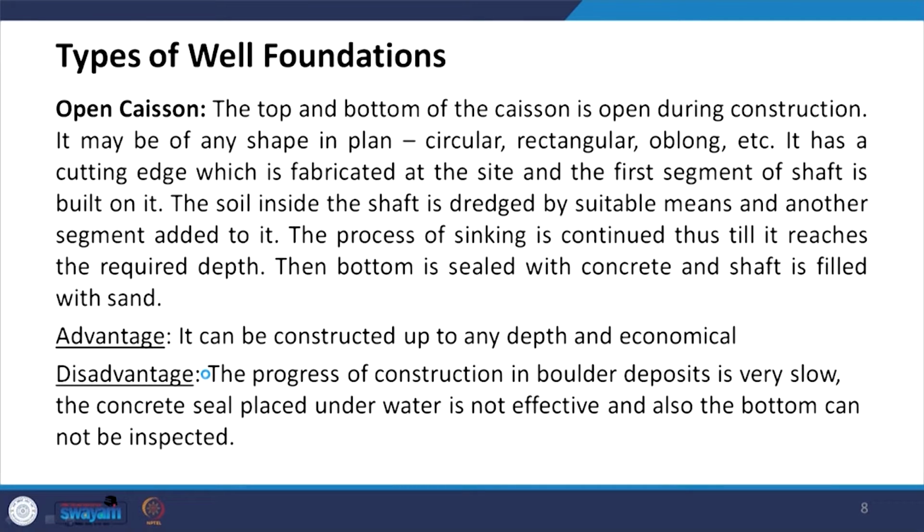So, what are the advantages of this? It can be constructed up to any depth and is economical. The disadvantages: the progress of construction in boulder deposit is very slow. If you have a hard rock stratum, then it will be difficult to cut, and this is slow. The concrete seal placed underwater is not effective, and also the bottom cannot be inspected. So, these are the issues with open caissons.